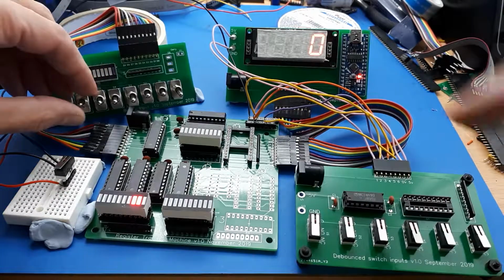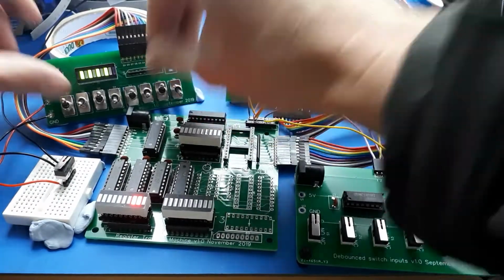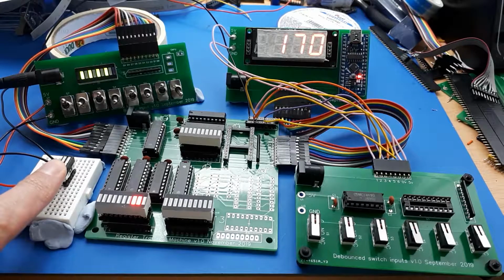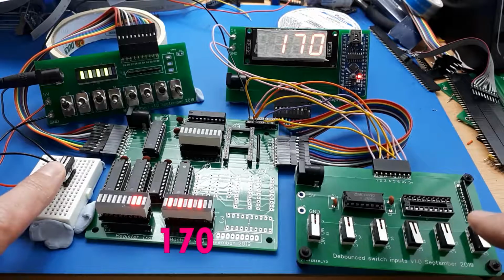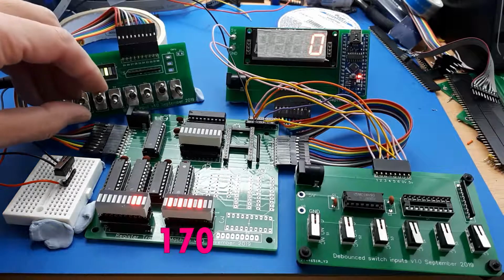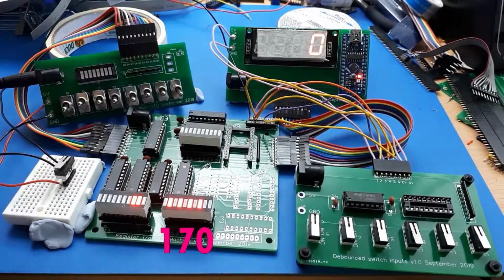Let's pick another number. Let's get a nice on, off, on, off, on, off. If we publish that, here's the publisher for publishing the keyboard onto the bus. It's 170. So binary 10101010 is 170 in decimal. So if I publish that onto the bus and store it in register 2, we've now got the value of 170 in register 2. And let's get rid of everything on the keyboard again, so the only place that 170 could possibly be now is in register 2.